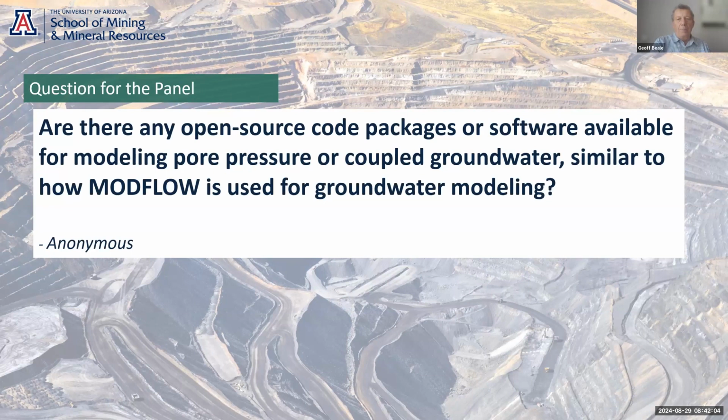So pore pressure is just the head of groundwater in the pore space or the fractures. So any numerical code will give you an answer on the pore pressure. We can use ModFlow, FEFLOW, any of the standard codes will tell you what the pore pressure is.